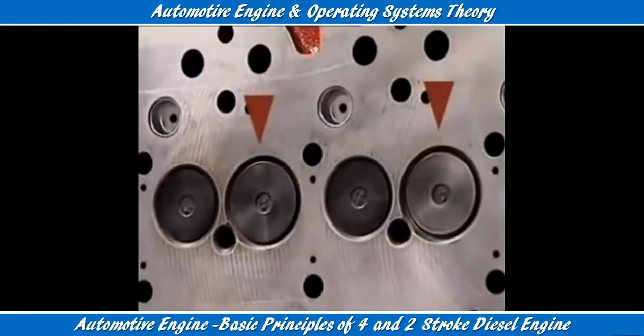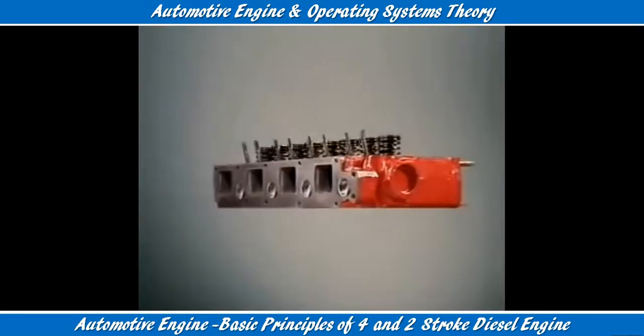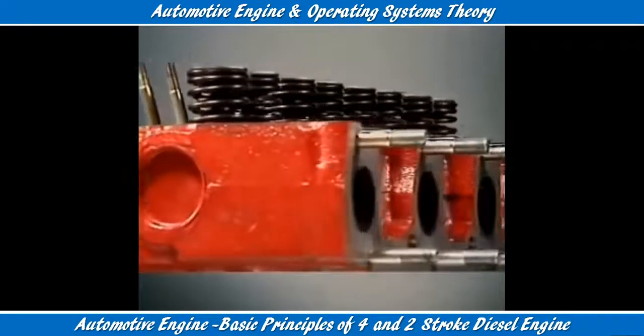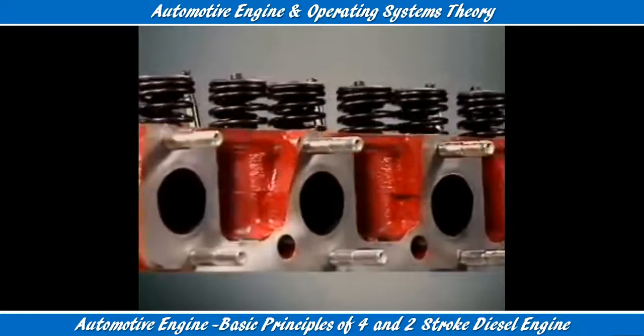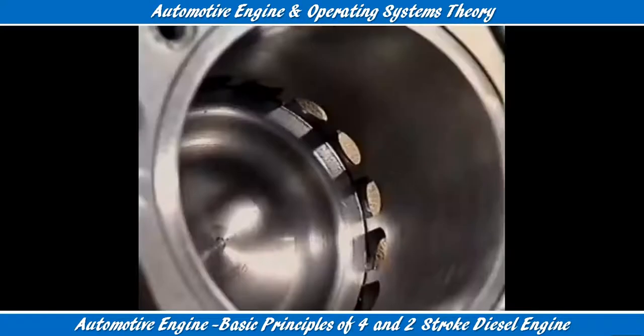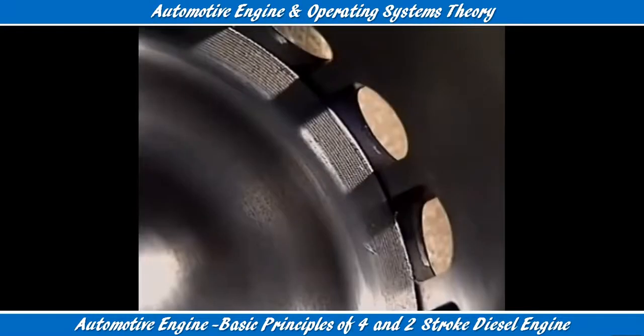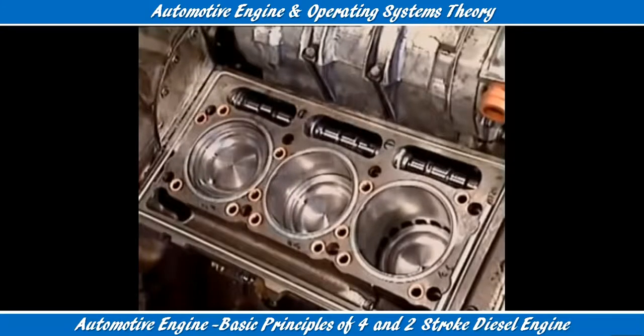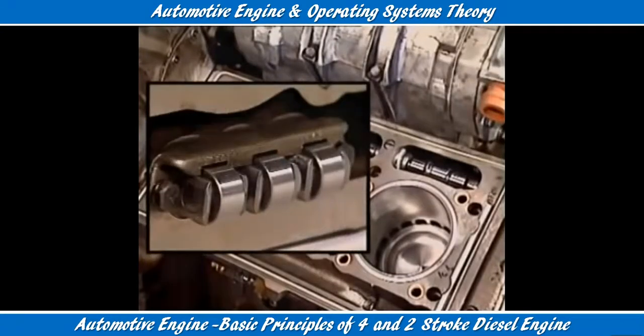The intake valve passes only air, so it's cooler than the exhaust valve, which releases all the hot gases after combustion. Valves in the diesel engine are usually parallel to the centre line of the engine. Small four-stroke engines usually have two valves per cylinder, one inlet and one exhaust. This two-stroke diesel engine lets air into the cylinder through inlet ports with no inlet valves, but its exhaust ports do have valves. Four-strokes and two-strokes use the same system to control their valves.